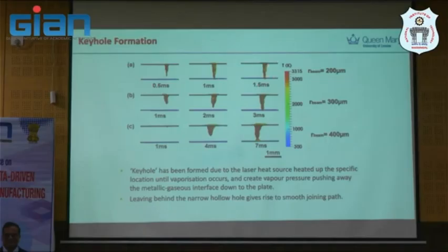And the map of this is actually on the keyhole surface, so we call it the liquid-vapor surface here. And you will see that the temperature is actually not homogeneous. There's some absorptivity effect present here. You see some zones are yellow and red. That means some, due to the term we impose here. And then when you increase the beam radius, the melt pool becomes larger and larger. So we try to compare.